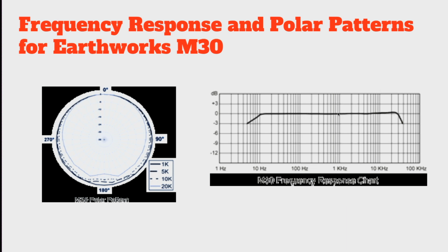And when we look at this, this is what we would call a flat microphone. When somebody says they're using a flat microphone, what they mean is a microphone that has a very flat frequency response when represented this way. We can also see that this microphone actually responds to much lower frequencies than the SM57 we were just looking at. In fact, it's pretty much flat down to about 10 hertz and then rolls off only by about 3 dB to probably 7 or 8 hertz below that.